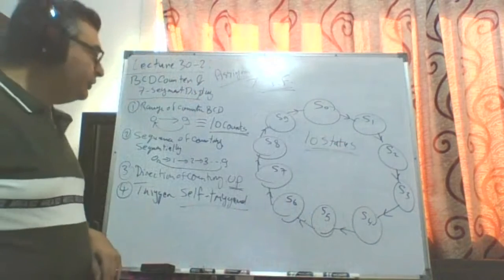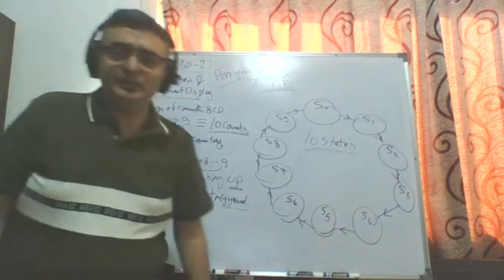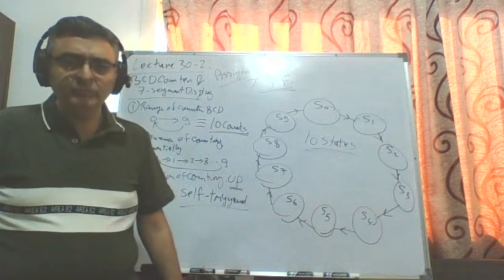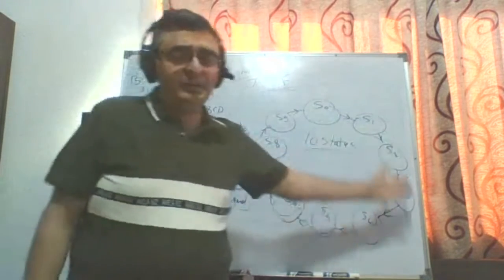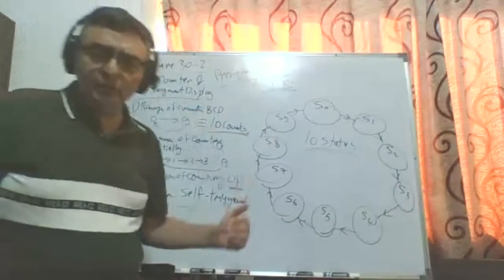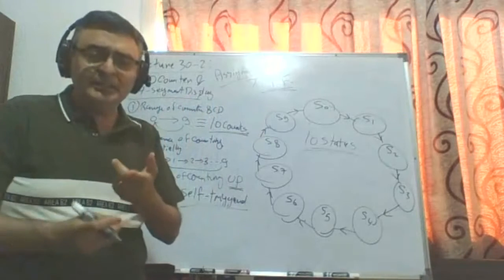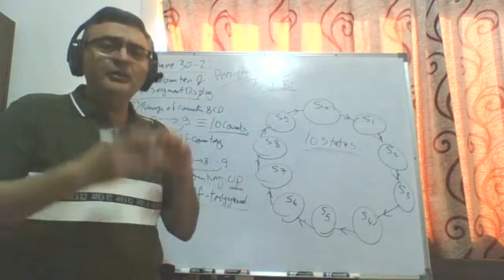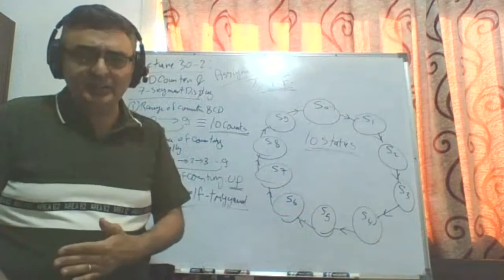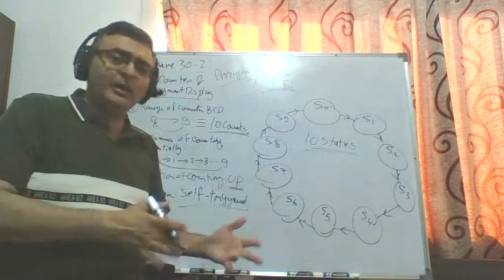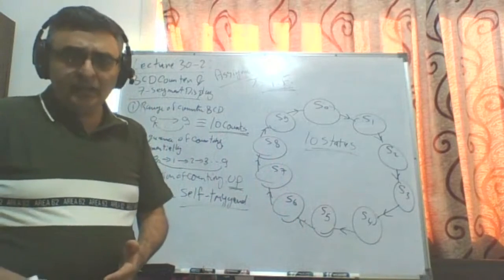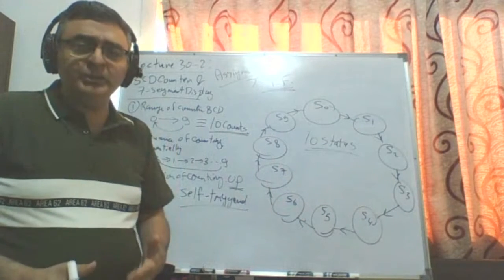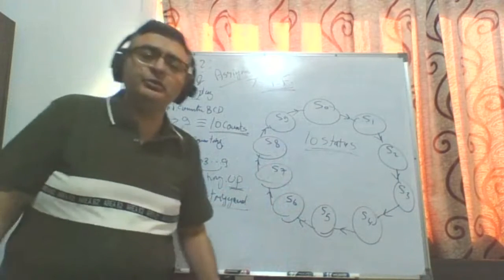Okay, so you go ahead and build it. Once we build the state diagram, we will identify how many states, accordingly how many flip-flops, the type of flip-flops, and start the design. From the state diagram, we can build the state table. From the state table, K-maps, we get the state equations. From the state equations, we can draw the circuit.